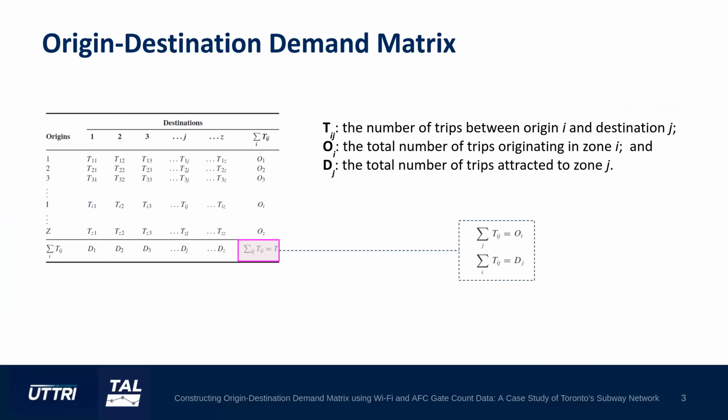We want to start defining an OD matrix and its importance in transport planning. The OD matrix is a data structure that maps trips to each origin destination pair in a given region. Its primary application is to support engineers, urban planners, and transit policymakers in understanding demand distributions and patterns, and eventually adjusting and improving the transit service. As we see on the slide, the only constraint for a balanced OD matrix is that the sum of trips in the columns is numerically equal to the sum of the rows.